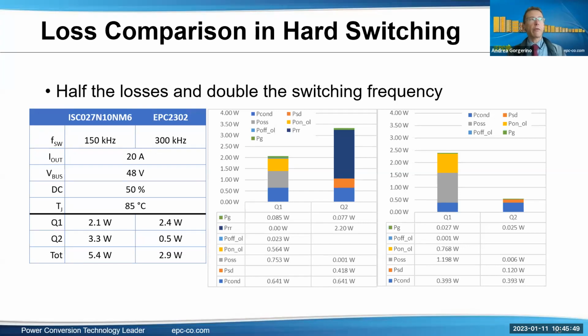So in a silicon FET, the RDS on increases with temperature, and that's the same mechanism with GaN FETs. I'm not sure about the question actually. All I can say is similar behavior for RDS on as a silicon FET.